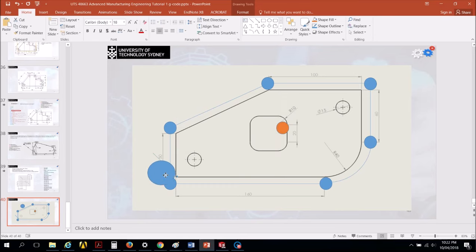Okay, so I start, for example, from here. At the beginning, I'm going to set the center point of my cutting tool in the negative direction of X with a value equal to the radius of the cutting tool, so minus R. Now just remember that we have to cut with half of the cutting tool at the beginning.